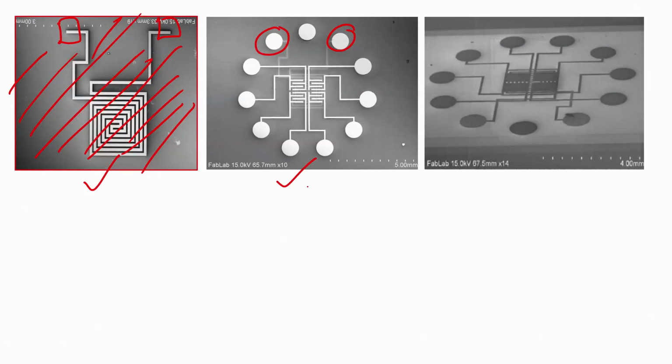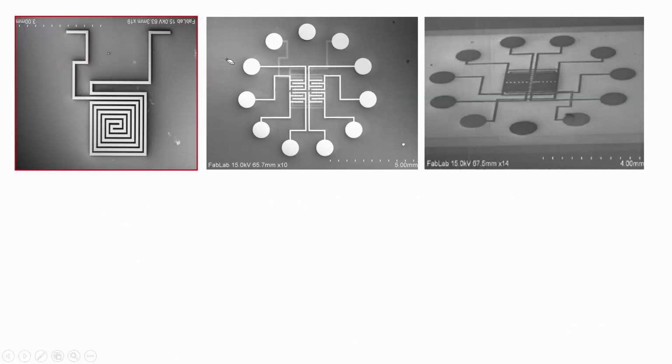On this chip, the next step is we want to have a piezoresistive material. How do we first deposit and then pattern this piezoresistive material? We can use several piezoresistive materials, including silicon; you can make a piezoresistor with polysilicon, or we can use a conducting polymer called PEDOT:PSS.